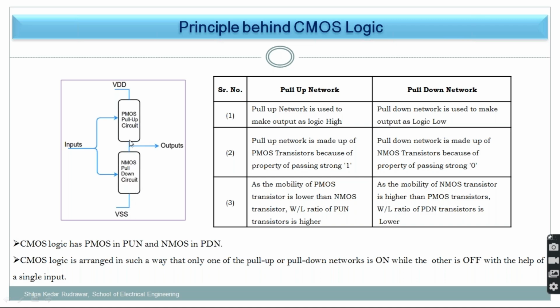In between, at the link where you get the output, the inputs are combined together to give the common input. There may be n number of PMOS devices or 3 NMOS devices connected in parallel or series. It is not that they are only in series or only in parallel. It might be in any combination. Same way for the NMOS.